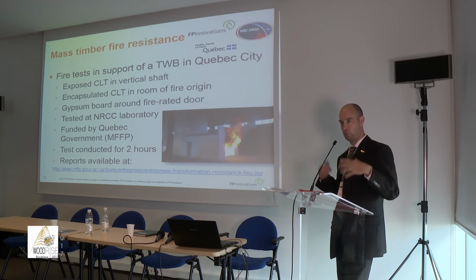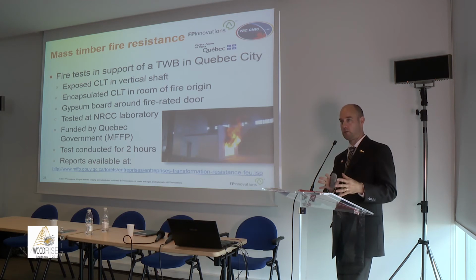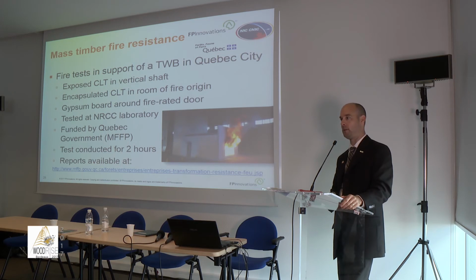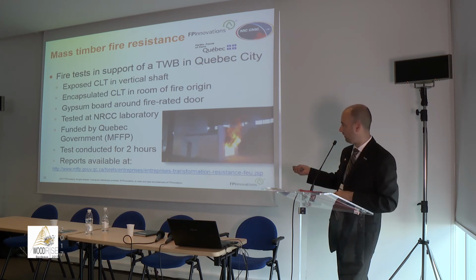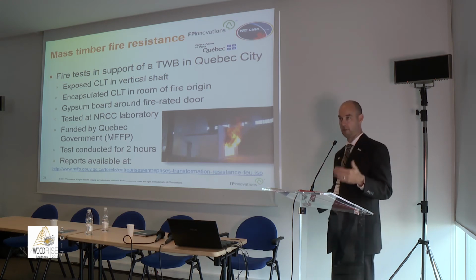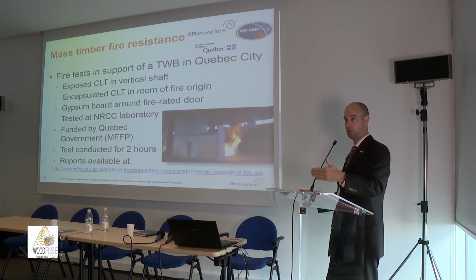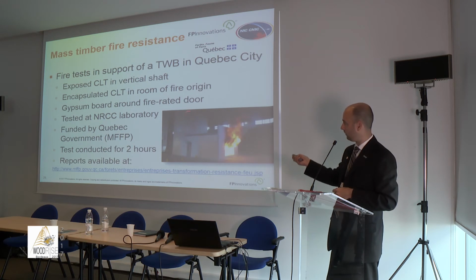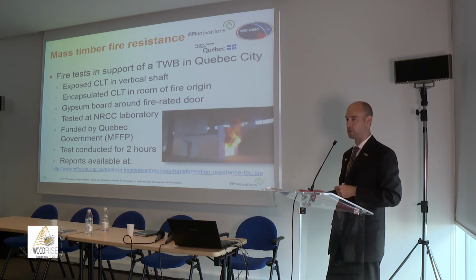We kind of replicated a one-suite apartment with furnitures and wood cribs to increase the fuel load. There was also a 40-minute door that was kind of simulating the door to external corridor, and this was a 3-story high CLT vertical shaft.